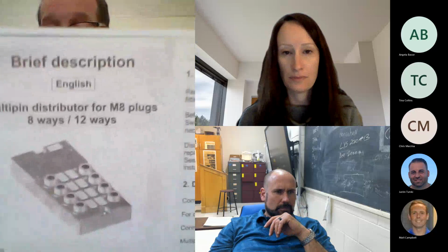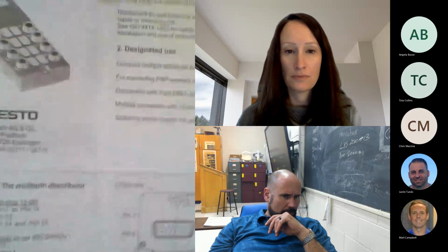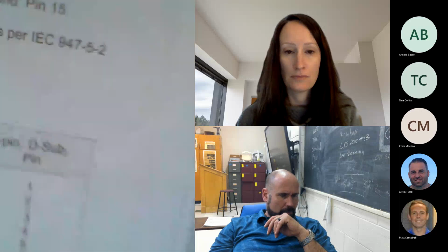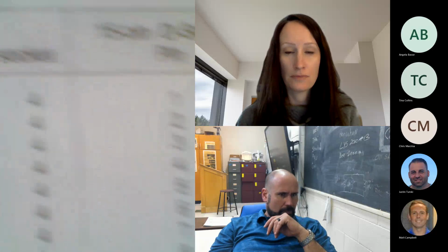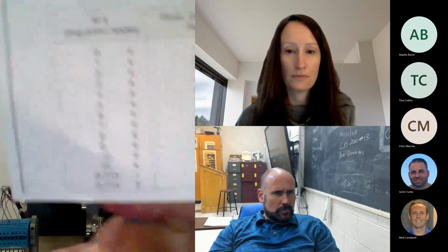This is something else I posted on there too. This is the multi-pin connector, they call it, that's on the Mech Lab. You'll look down the bottom here, you can see the pinouts right here. For every socket on the multi-pin connector, there is a specific pin on your D sub connector here that it's associated with.